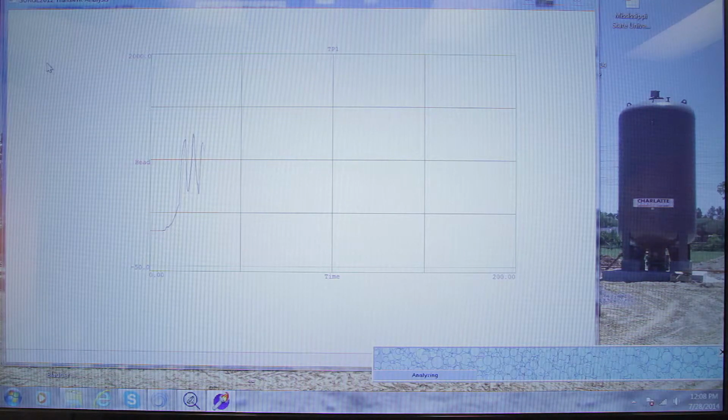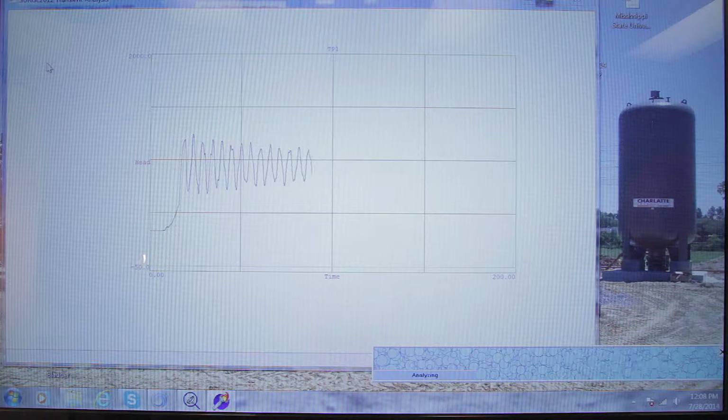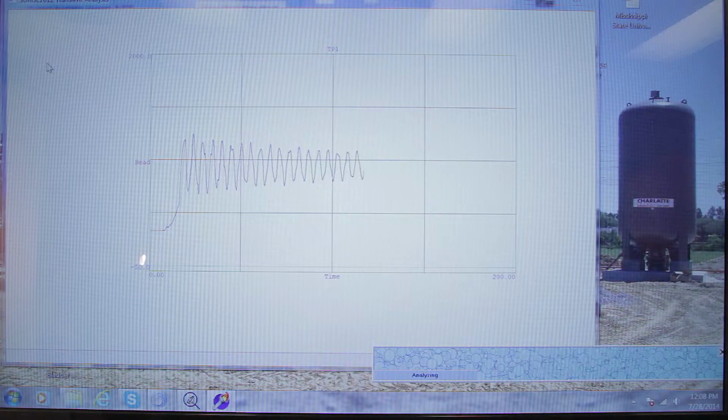So we accept the energy, but the issue going on right here is that somebody did not turn off the booster pump. So what happens is we accepted that 500 psi pressure wave, which occurred when they closed the valve in 2 seconds. So we have that upsurge that we accepted the energy, but then that wave oscillates down the piping system back towards our pump, and we drive the pump to dead head. Okay? With that pump still running, this is what we're simulating.